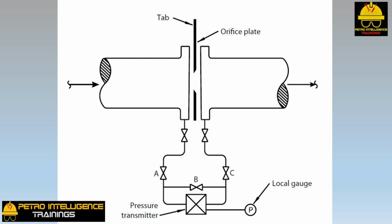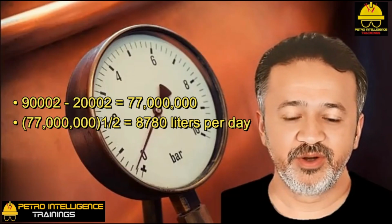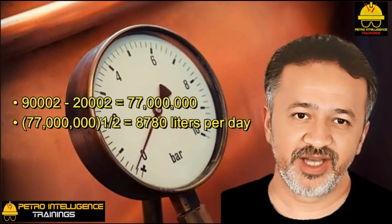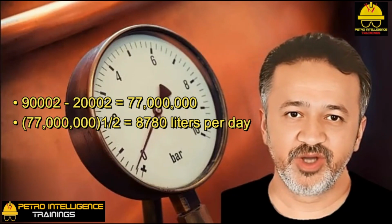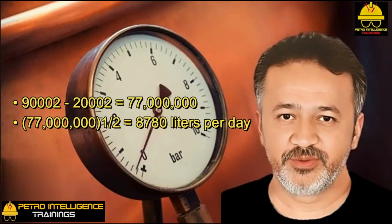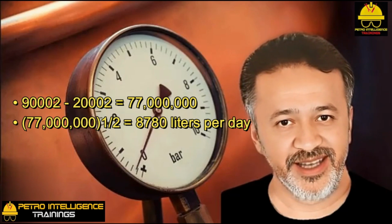The answer is not 7,000 liters. Why? Because flow varies with the square root of the orifice plate pressure drop. To calculate the correct acetic acid flow, 9,000 squared minus 2,000 squared equals 77 million. 77 million to the power of 1/2 equals 8,780 liters per day.